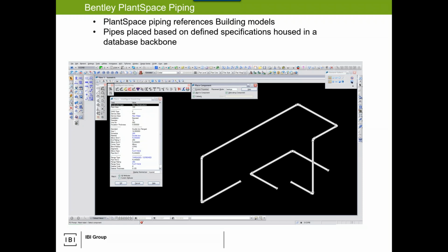And the reason for that is in the plant world, you don't model rubbish. You shouldn't do that in the building world either, but you can't in this world. If I'm modeling this pipe, in this example I'm showing here, RW is raw water. I need to know I'm modeling the raw water pipe, the pipe that's going from the lake to the plant. I need to know the material. And if it's flanged ductile iron, it's going to have a limit on what I can actually model because of limits of gasket sizes, limits of flange sizes, the requirements to bolt your flanges together, and the limitations of pipe spools.